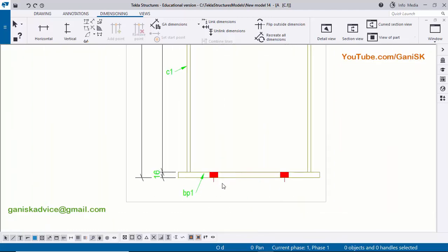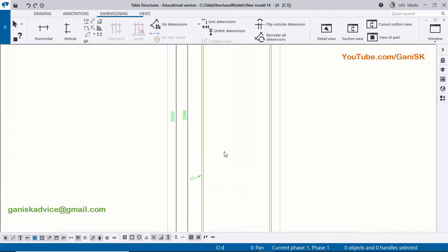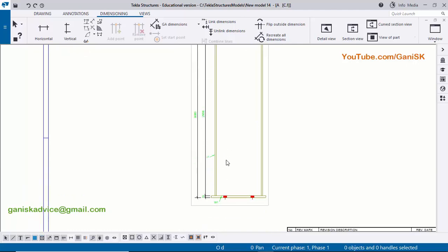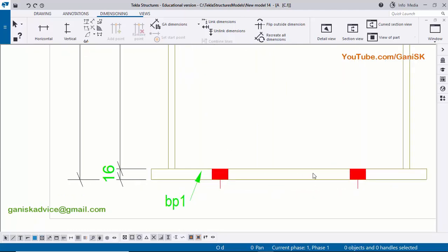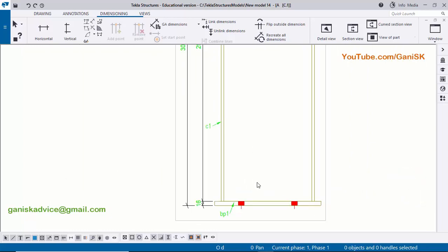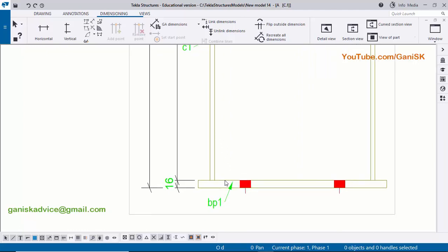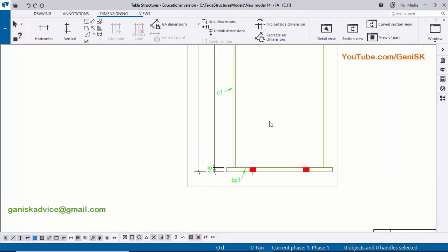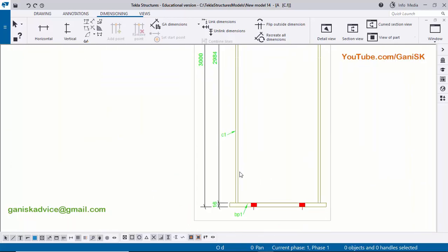Now coming to this part BP1, we have already generated this I section profile single part drawing and base plate single part drawing, so no need to worry about these dimensions of these holes and the length. But here in assembly drawings we need to give the relation between a primary part and secondary part dimensions and welding symbols. That's it.